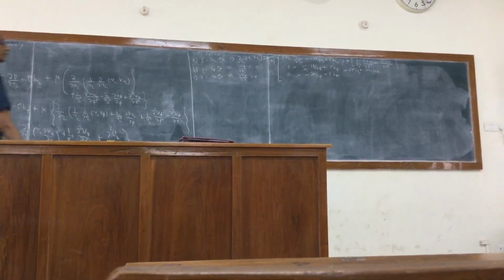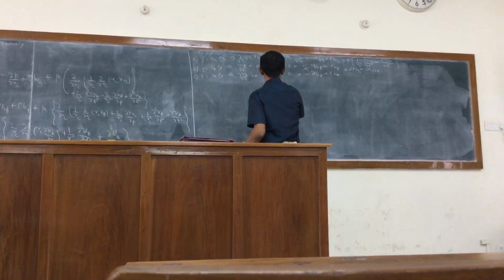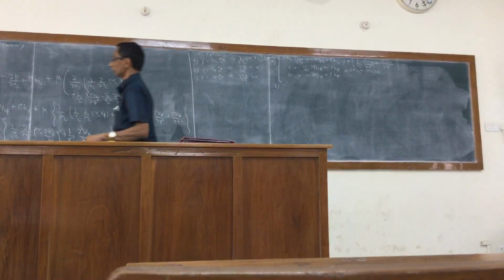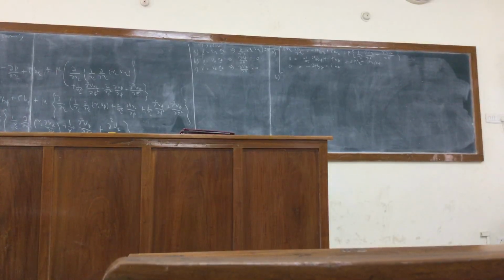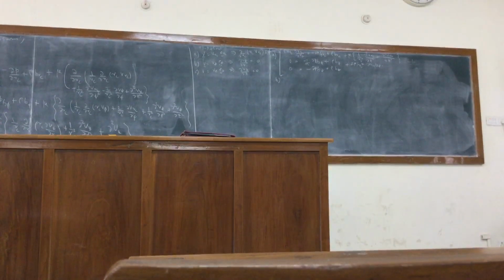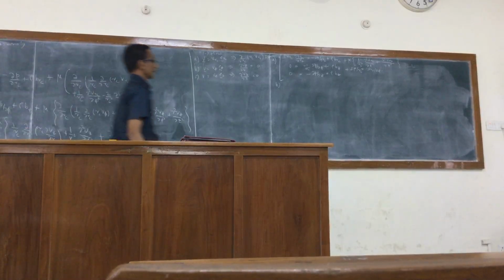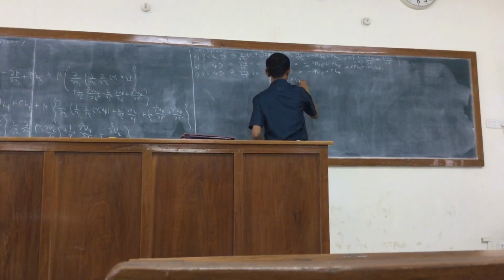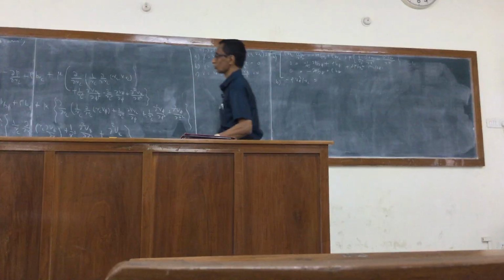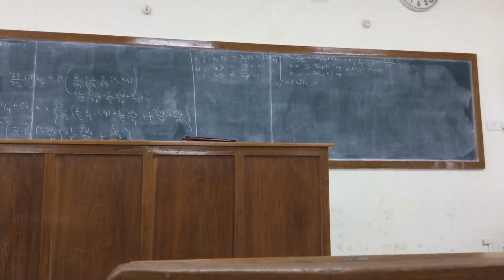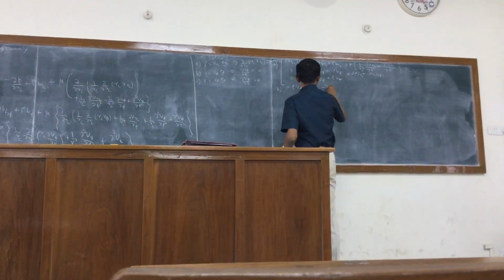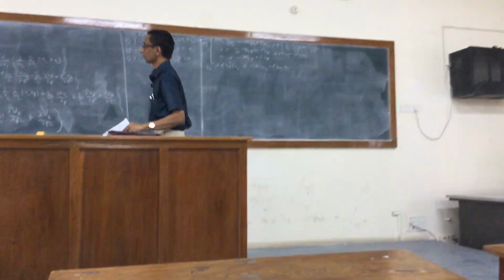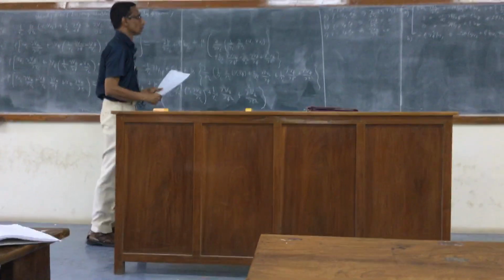Right? So this is for case A, and now for case B, where V equals V phi. So for the equation of motion, this is 0, so you're going to get minus rho V phi squared by rc. Now I'm writing the rc component: minus rho V phi squared by rc is equal to minus dp by drc, plus, what are the terms that are going to contribute?